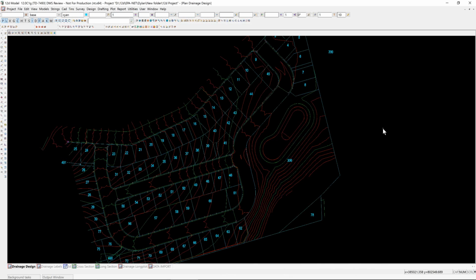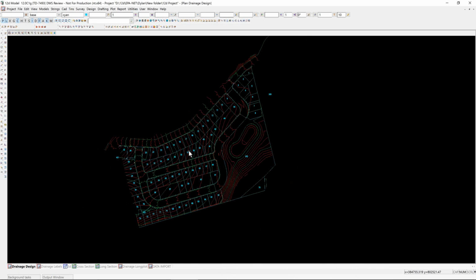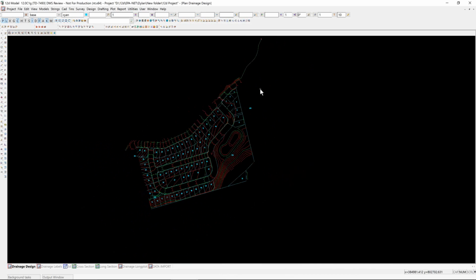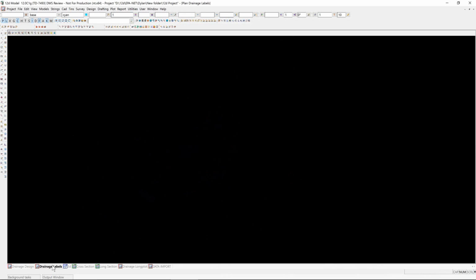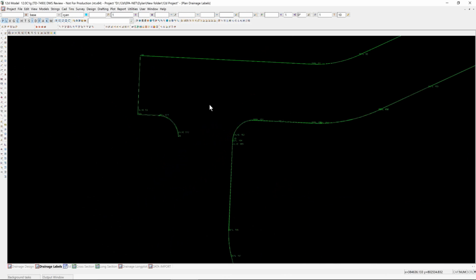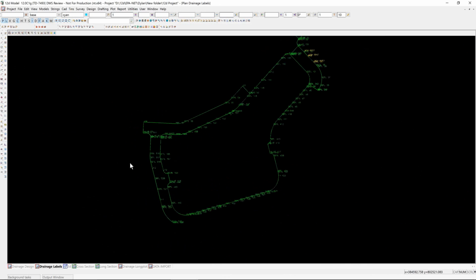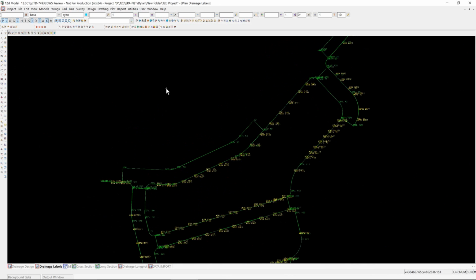What we've done here is we've taken the AutoCAD drawing and we've taken out the drainage string, which is basically that green line to the north or northeast of the system. That's the start of the drainage string. And we've converted it to a super string, and we've converted it to a drainage string. So I'll start with a conversion to the drainage string.